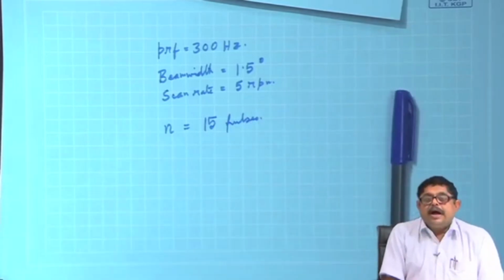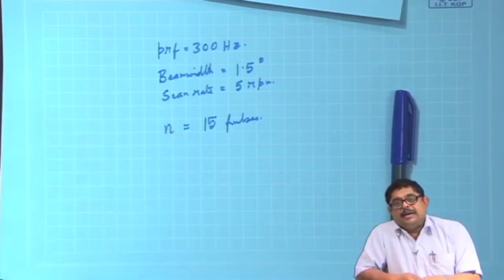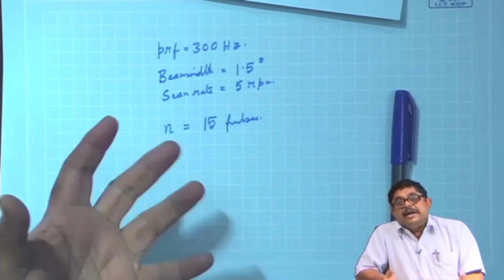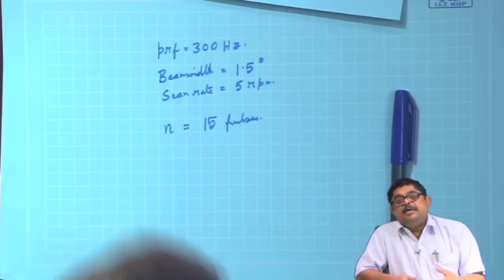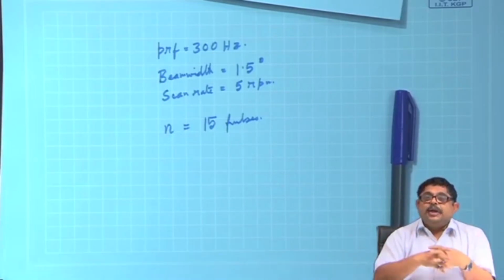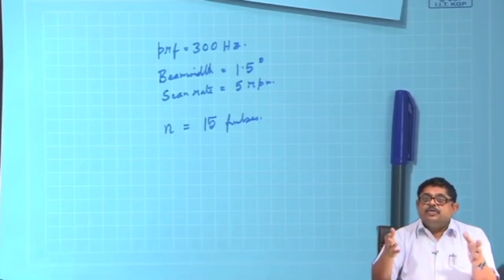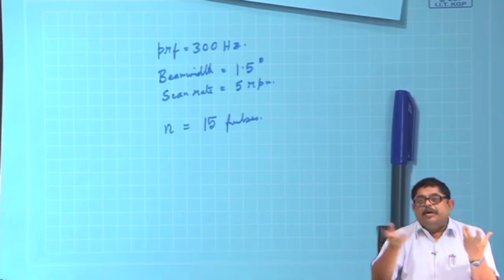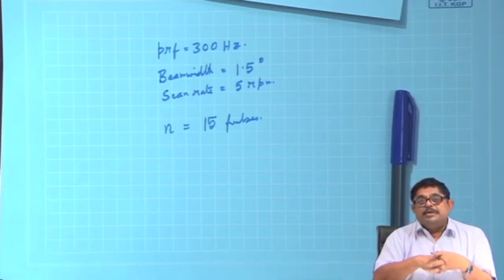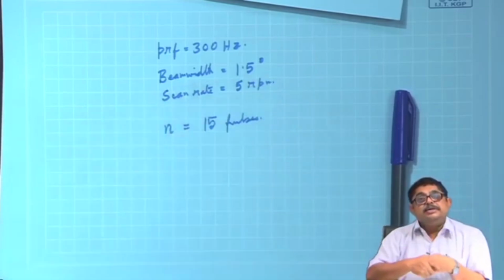Now, you can ask: though we have assumed there are no noises, in real life noise will be there. So, does the SNR of the system improve if I do integration? Because when I am integrating, I am adding, so the signal power and noise power both are getting added. So, how can I say that my detection will improve? One thing is that it is coming closer to the receiver sensitivity, but it is also increasing the noise.